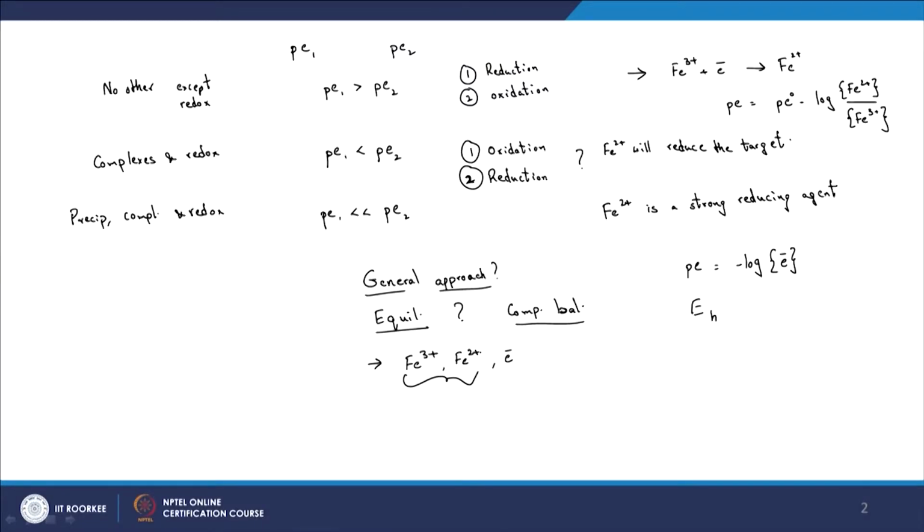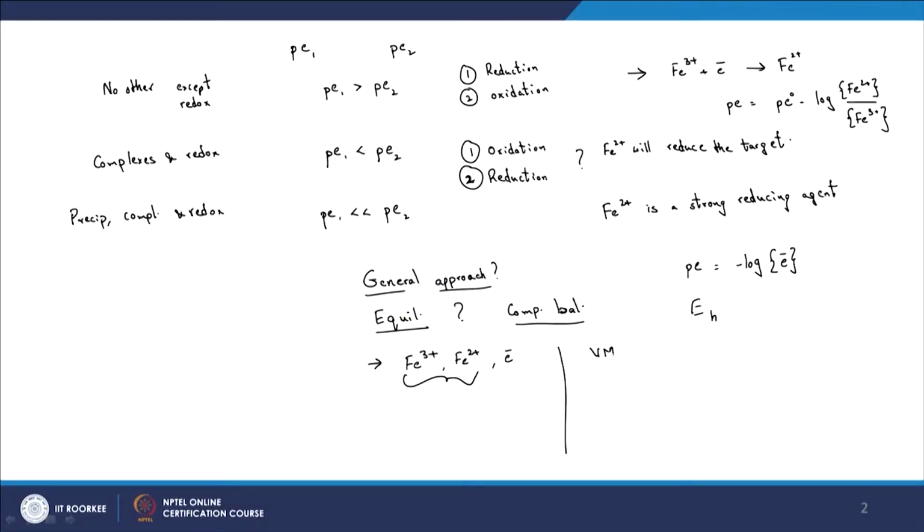But obviously, you then need to look at manipulating the other two components too. And how does Visual MINTEQ calculate this? What is this software about, and what will it help give me an understanding about? Keep in mind that Visual MINTEQ doesn't give you any idea about how fast or slow the reactions are. It is software that we can use to understand what the system would be if and only if the system reaches equilibrium. So when you use it to analyze redox processes or reactions, keep in mind that you are only understanding the conditions that would prevail at equilibrium. The kinetics play a huge role, so that's something you need to calculate by looking at the relevant rate constants or such.